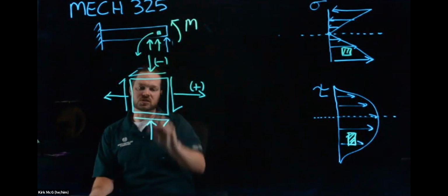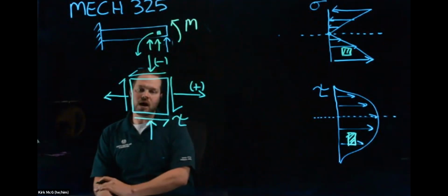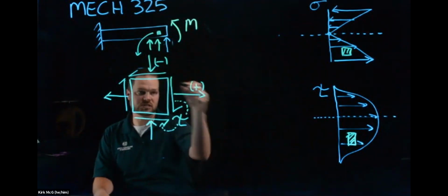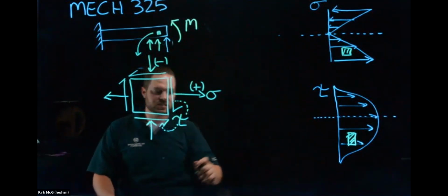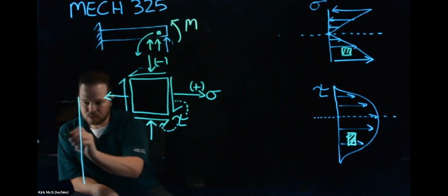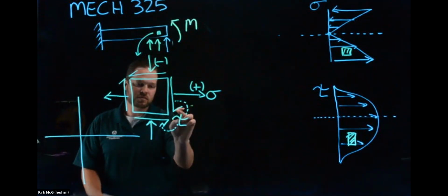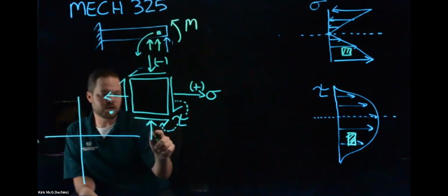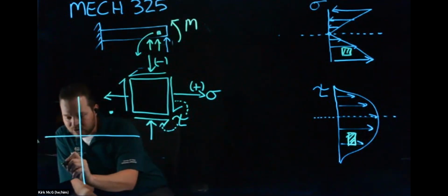So then the question is, how do I use this? Well, what I can do is I can understand, and this is my tau. These are my taus, shear stress, normal stresses. These are my sigmas, okay? Well, what I can do is convert this into what's called Mohr's circle, which I'll draw over here. So I have some positive shear stress, so that comes like here, let's say. And then I have some negative causing compression. And in this face, this is negative, so that's down here.